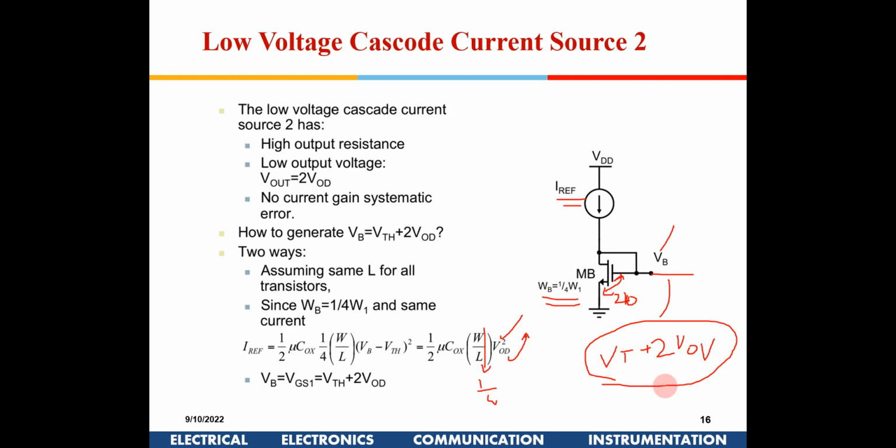And this voltage is generated because we are passing this I ref current, right? Yeah, by passing this reference current. But sir, in a MOSFET, isn't it the reverse? Like if we apply VGS, then only I ref will flow. No. See, for all these circuits, we have to first generate an I reference. So I ref will automatically create a channel and it will develop this potential difference. And this is happening because we are assuming that I ref is an ideal current source and it will always supply the current. Okay, correct. So we will generate I reference. We'll see those circuits.